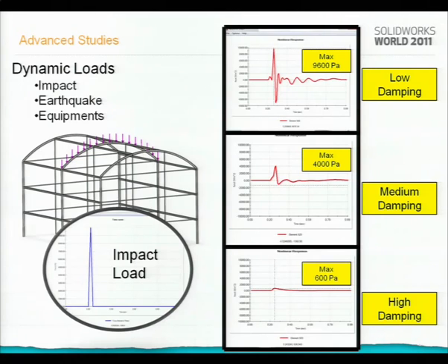The bad news is that we cannot get the damping from numerical simulation, right? Damping should be taken from the actual structure, and you can tell me, okay, Jose, but I don't have the structure yet. So we have to take the damping from some similar structure, from a test on the structure, right? There is no way to obtain the damping with simulation in this kind of structure.